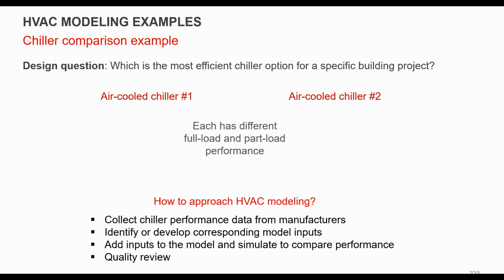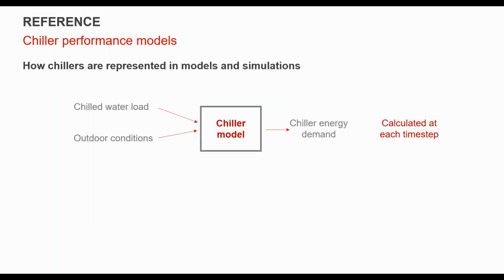First, you're going to collect the data. So go to the manufacturers, get the cut sheets, spec sheets, figure out how to translate those cut sheets into model inputs, and then simulate them and compare the performance and do a quality review. So what goes into a chiller model? In a chiller model, this is, again, getting a little more into the weeds of what you actually need to look at.